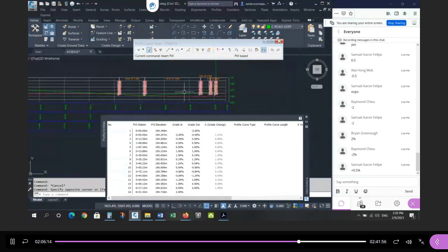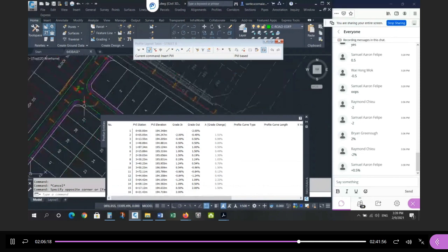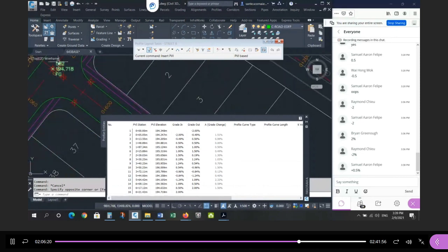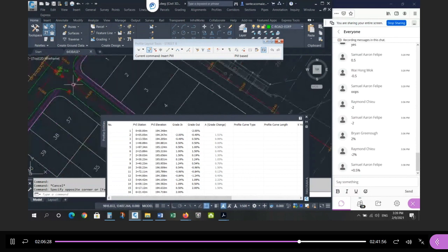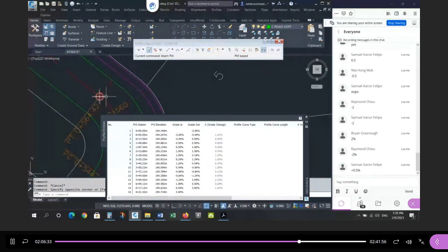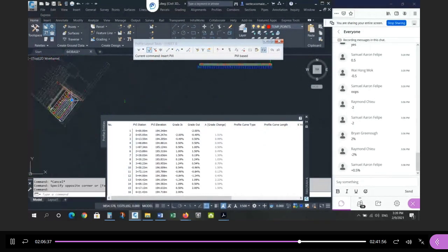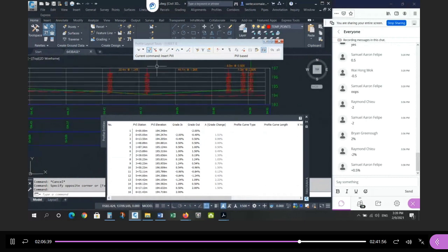Now from there, we're going to go up to the first bend, right? Don't forget what's happening in the plan. We just designed this elevation here. So we went down here with a 2%, then we went down to here with a 0.5%. And now I want to design from this low point to the end of this curve. I want to establish this elevation. What's the slope from here to here going to be? Which is this stretch right here, which is this input right here.